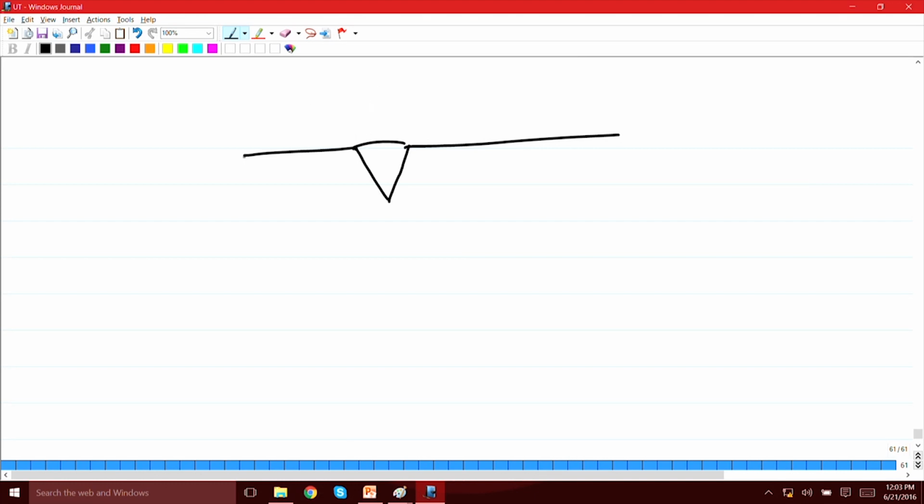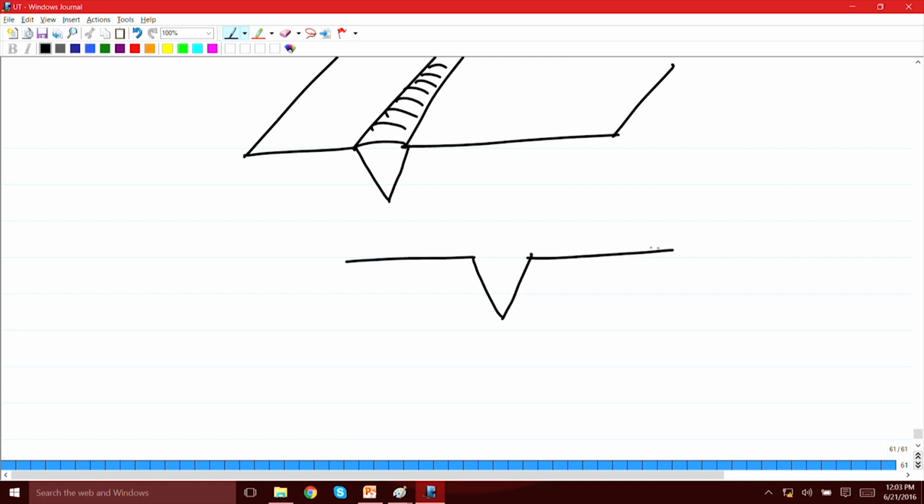So, this is the weld, okay, and if you see the view, so this is across this interface, okay, these two plates are joined. Okay. So, this will be the weld. Okay. So, in this case, as you would have realized, you cannot use a normal probe, because in that case it will simply go like this. Even if you keep it on the top of this, there are these surfaces, the welding joint is here. So, it is not appropriate to use normal probe in this case.